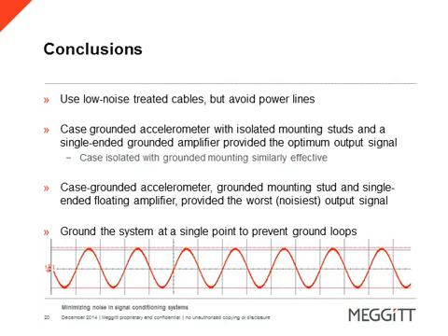We also discussed piezoresistive pressure transducers and piezoresistive accelerometers having the benefit of a low impedance voltage output into a differential amplifier. This scheme provides a measurement chain less susceptible to noise inputs. The output cable shields still adhere to the single ground point rule to minimize noise problems during test and measurement applications. We also touched base on the IEPE Isotron accelerometers, and having them maintain the same guidelines as the single-ended piezoelectric accelerometers. However, since the charge converter circuitry is built into the accelerometer, a low impedance output voltage provides the signal less susceptible to noise interference.